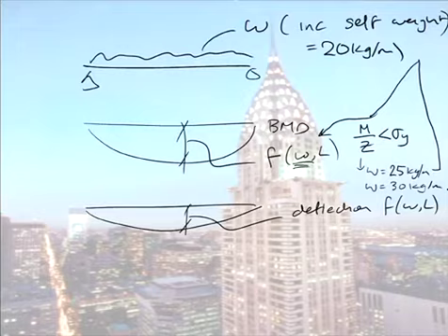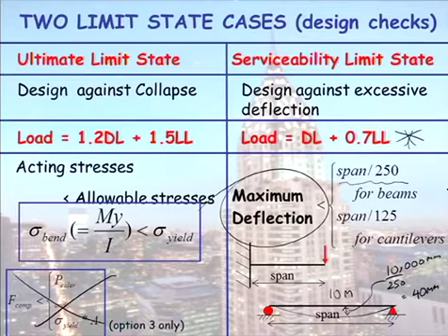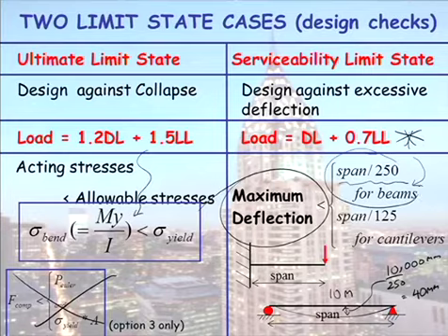So it's quite an easy process really. In this design, I've been through it, you're doing a strength and a deflection check, so an ultimate limit state check and a serviceability limit state check. Your dead and live loads are the same for both, it's your load factors that vary. When you have your bigger load factors in there, that's when you're going to do your strength check. With your smaller load factors, you're then going to calculate a deflection and ensure, for a simply supported beam, it's less